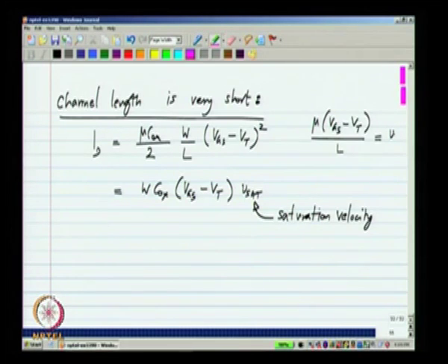Now, because of these reasons, the transistor current does not obey an exact square law dependence with Vgs. Okay. And also another thing to keep in mind is that the regions are not abruptly divided into, oh, here we have velocity saturation and here we do not. Okay. Like all physical phenomena, these happen continuously.